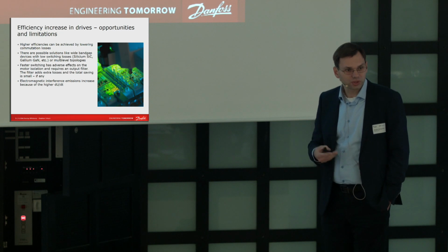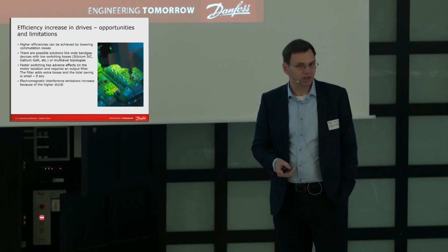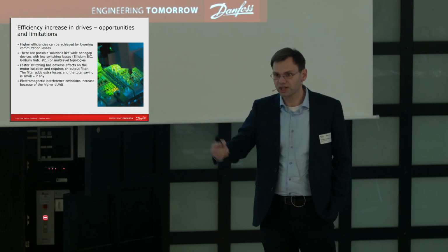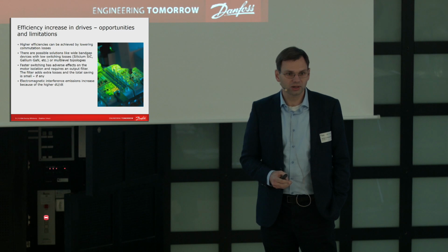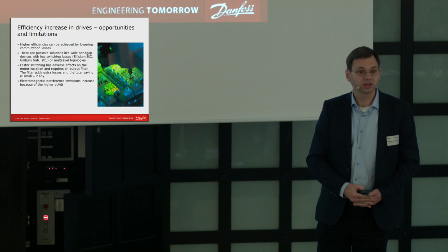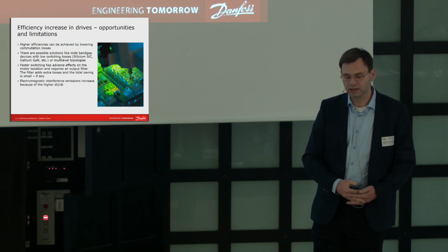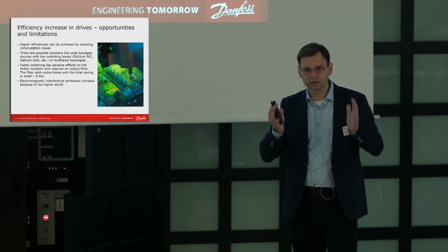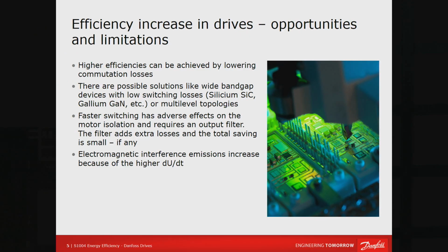There are some possibilities to improve the efficiency of a drive. Of course, we have seen in Konrad's presentation also a slide about the falling price of silicon carbide. We all know that. Actually, Danfoss is building a joint venture with General Electric in the state of New York, an entire factory focused on building SiC power modules, but not for motor drives yet, because the issue is that very fast switching destroys the motor insulation.